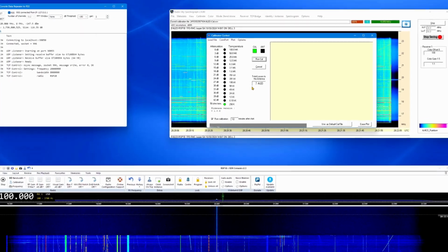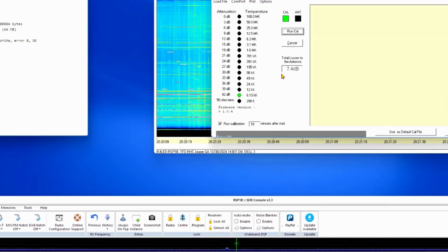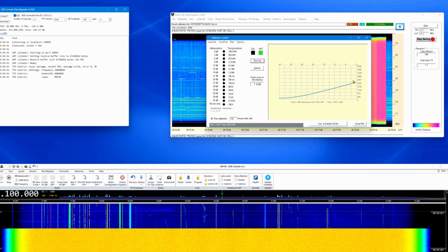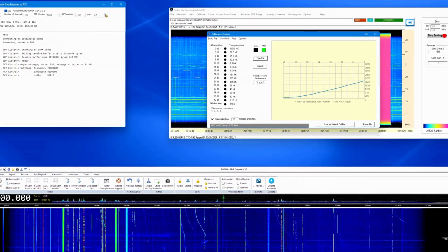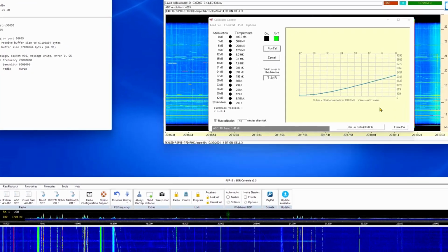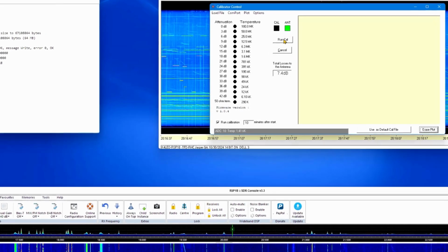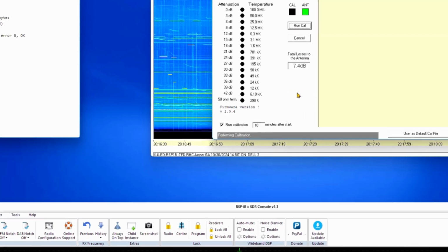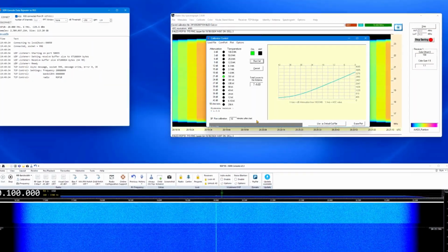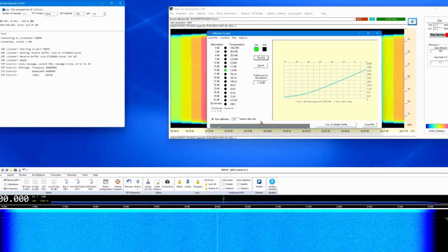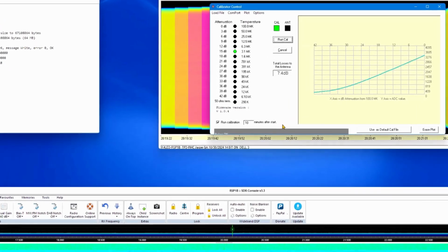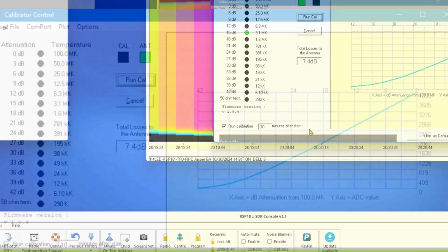There is some interaction between adjustments. Next, set the plotline top end to the top right corner by only adjusting the SDRC2 RSS gain number. A higher number moves the plotline higher. A lower number lowers the plotline's top right end. Settings interact slightly, so multiple calibration plot runs are required. At least 3 or 4 iterations are necessary to get the plot to the far corners of the plot area. Eventually, you must call it good enough and be happy with the results.